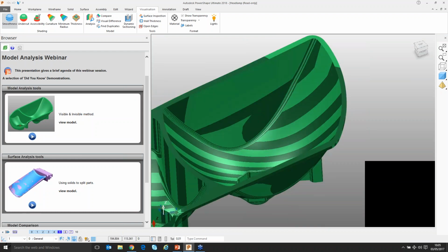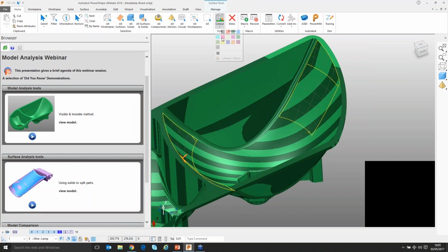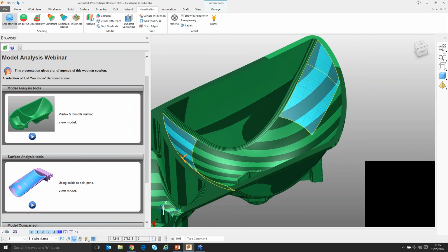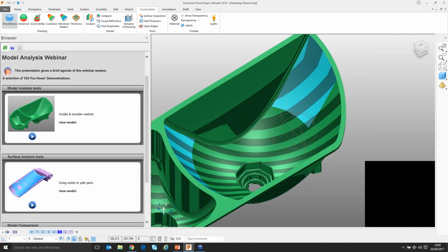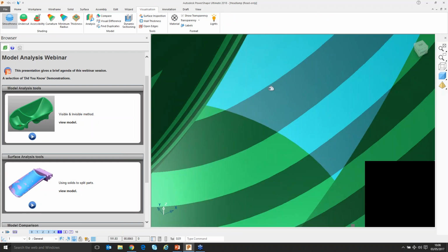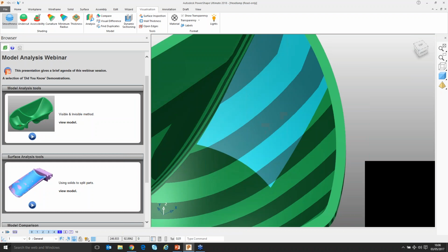And if I were to select that surface there and go for the home page, and let's just change the color in that region to something like blue. Can you see there that we have separate surfaces in here, but the curvature going from one to the other is, first of all, they share the same edge, C0, then they have the same face, C1, and they have the same curvature. I can see no difference in that from here to here, so that tells me they are C2 or above in that area there.